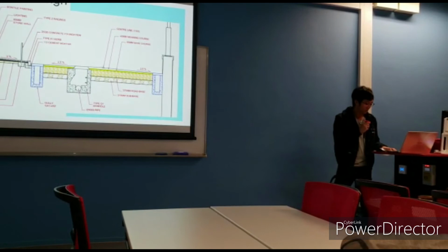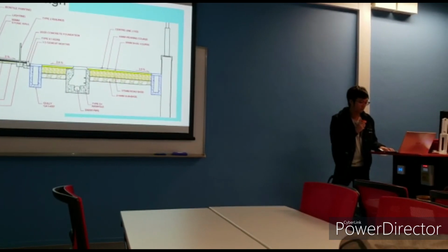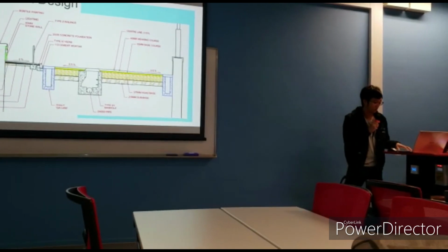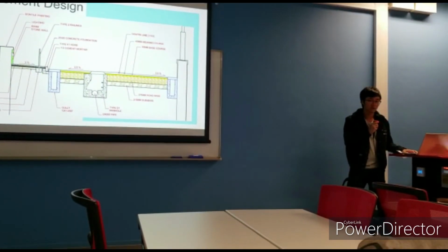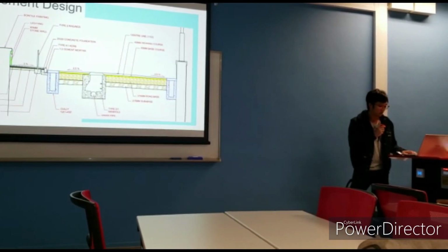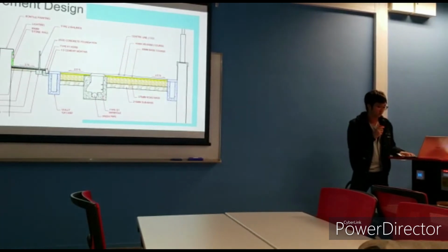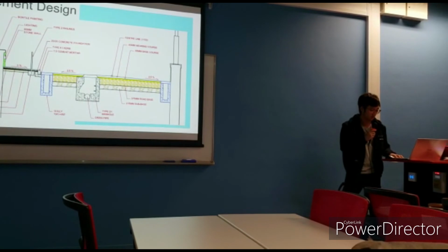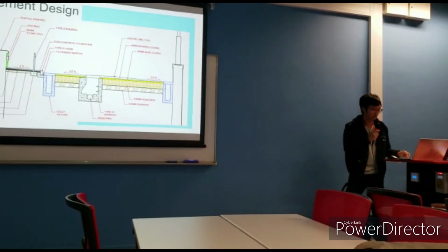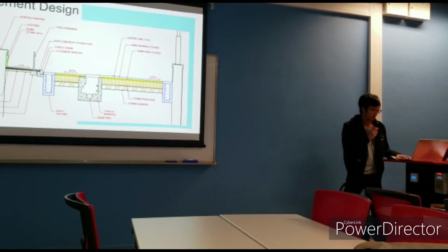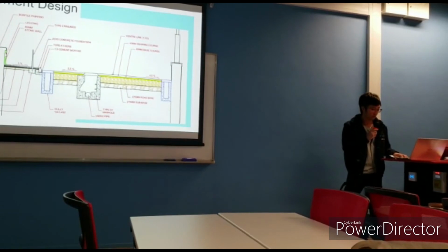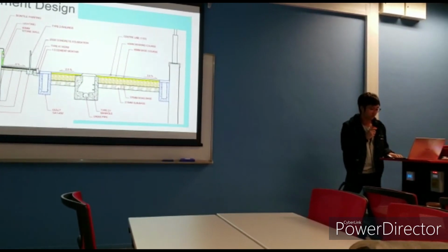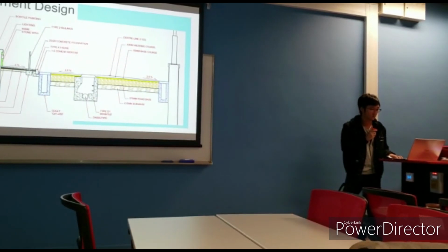And the carriageway slope will form 1 in 25 slope to guide the water into the gully, and the double line wall marking number 1001 will be painted to separate two direction line of the EVA access. And our footpath will use the 60 millimeter paving block and formed 1 in 13 slope.